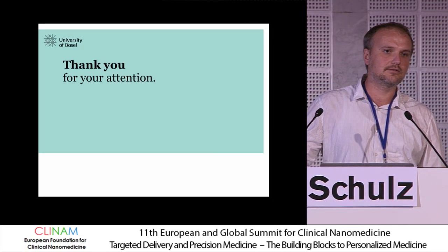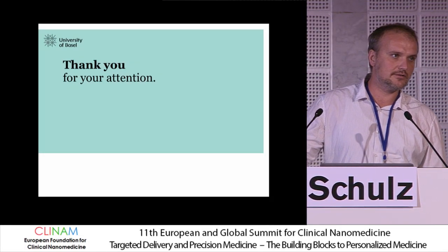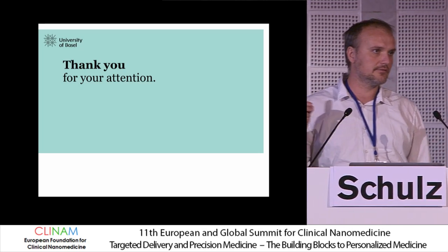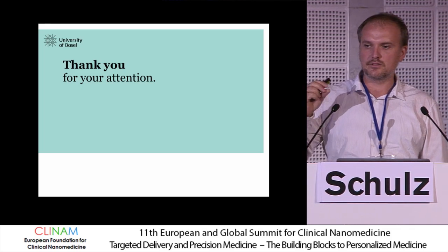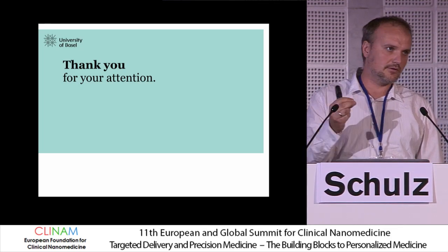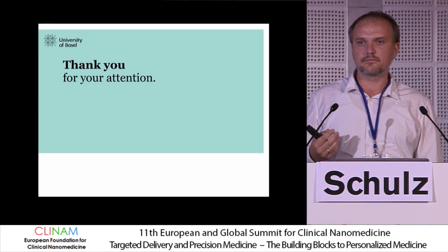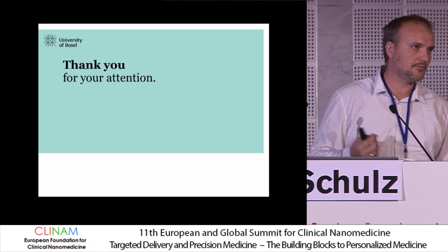But as I told you, the pixel size is not yet the resolution. The resolution is always limited by the source size. There are 4 different modes of the scanner where you adjust the source size. Of course, the smaller the source, the fewer photons, the fewer X-rays you have, and the longer the exposure time will be. So up to 10 hours you can take.